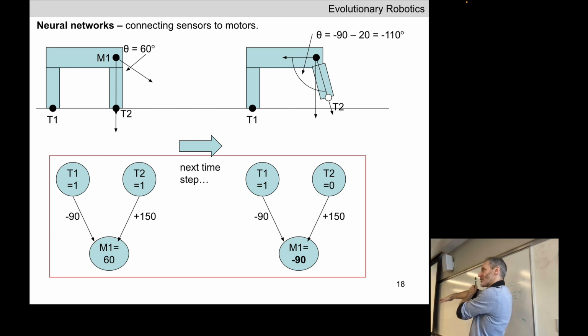So the joint normal is a 3D vector. By defining that vector, we're indirectly defining the 2D plane, which is normal to that vector. So if I give this particular joint a vertical normal, 0, 0, 1, when the snake starts moving, these 2 parts are going to rotate like this relative to one another.